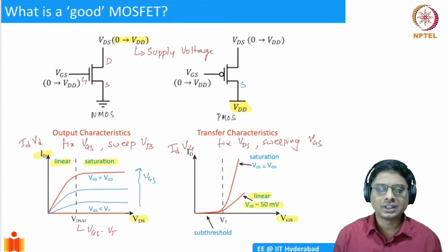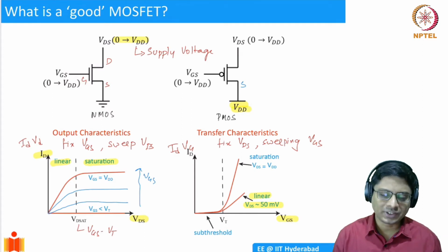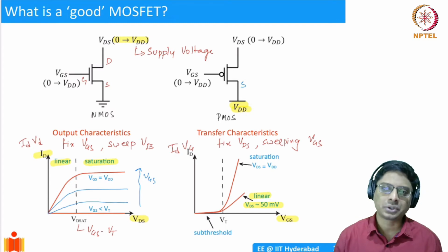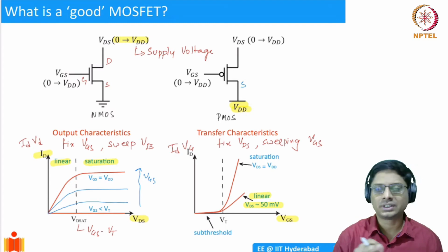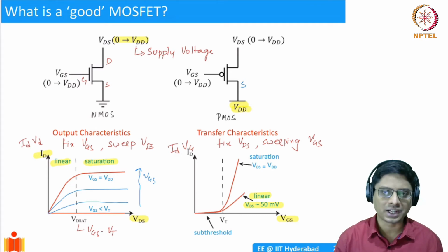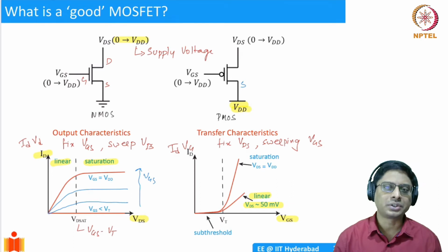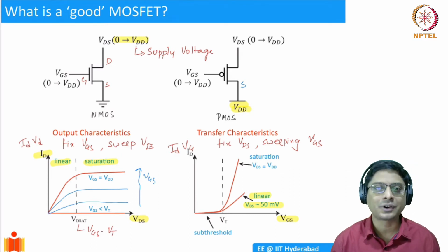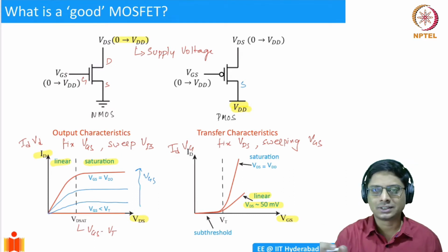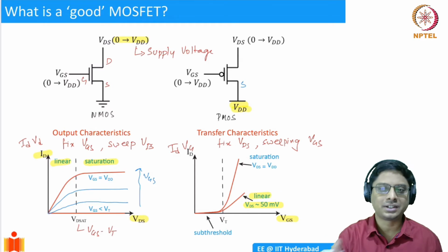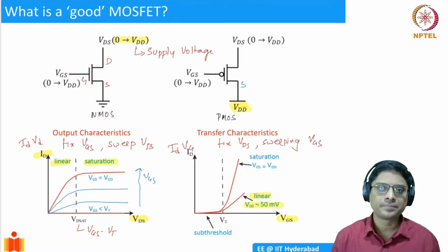Why do we do this? Well, one of the reasons is that we are using an N-type substrate. We want to make sure that the source and the channel junction is always reverse biased. Similarly, the drain channel or drain bulk junction is also reverse biased. So since it's an N-type substrate, we connect it to VDD, so it gets reverse biased. We don't want to accidentally forward bias the source channel or the drain channel junction. That's one reason. The other reason is it makes it very convenient.